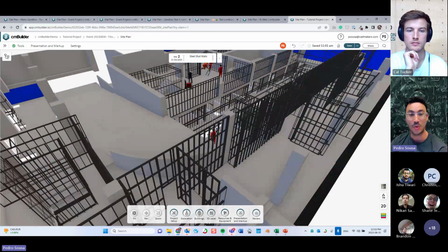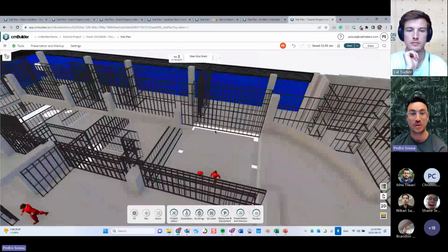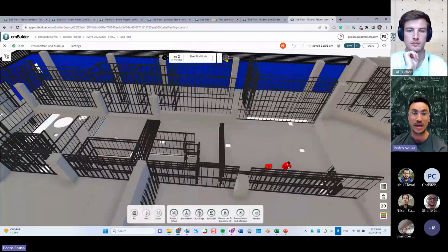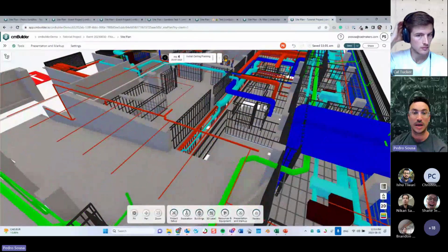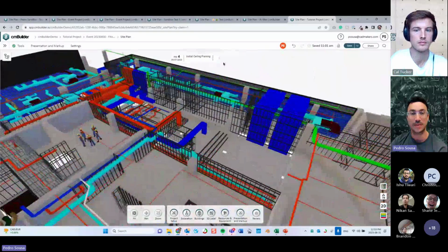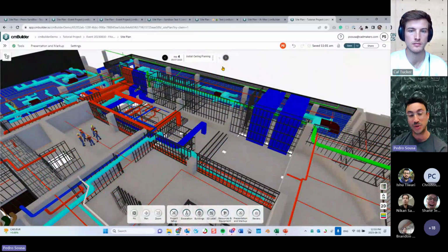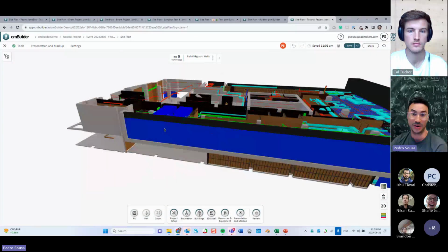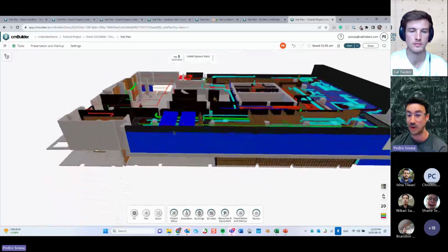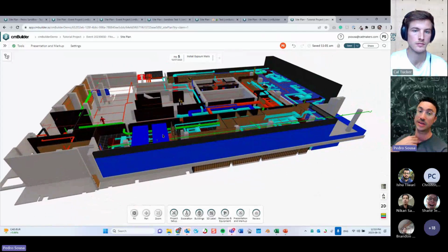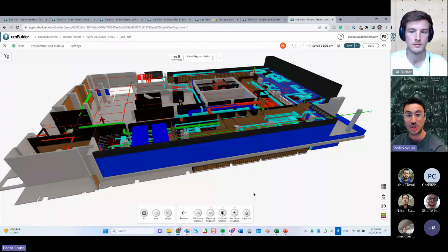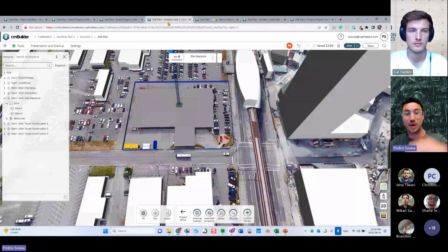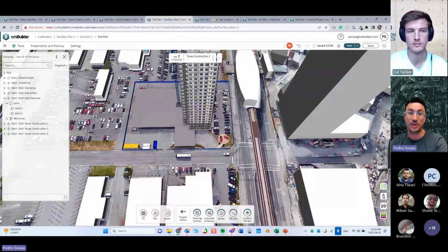And when you go further, you can see that only the steel stud walls are executed. When you go next, now you have your MEP stud stuff going on. And then you install your ceiling framing and so on and so forth, right? So the idea here is to isolate a level if you can from your 3D model, or isolate that level inside cmBuilder or use a section to create that isolation or look at one level specifically.